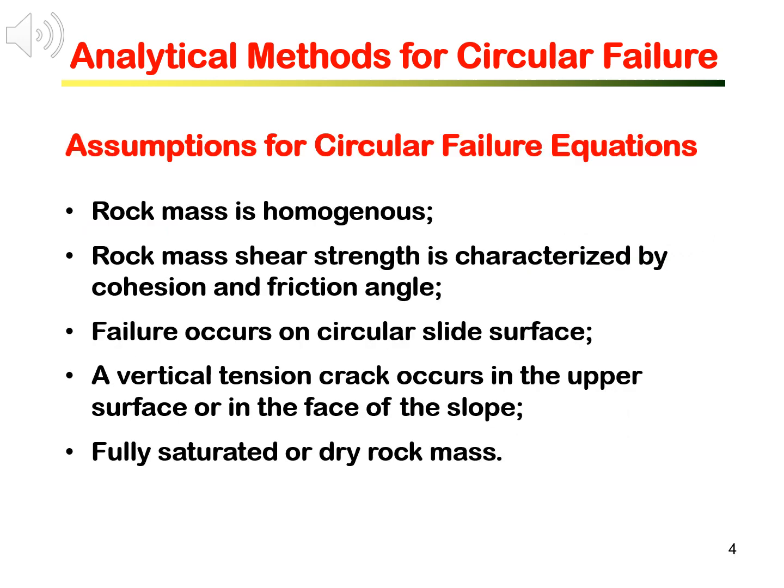As we mentioned earlier, analytical method requires a number of assumptions when formulating the equations. The assumptions used for circular failure equations are: 1. Rock mass is homogeneous. The discontinuities such as joints are not considered. This assumption is valid for completely weathered, crushed, very highly fractured, and very weak rocks. 2.